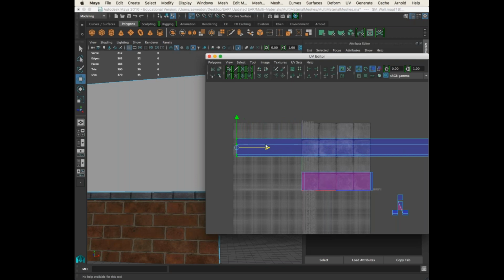So if you don't want to go through and tile it inside of Unreal, because I want to actually use this for like a 4-piece instead. So again, this is one of those cases where, yes, I'm wasting that 0 to 1 space, but I also know that I'm going to be using these concrete tiles for a much larger piece. So in that case, I wouldn't want to tile it more in Unreal, right? I would want to just tile it in Maya.